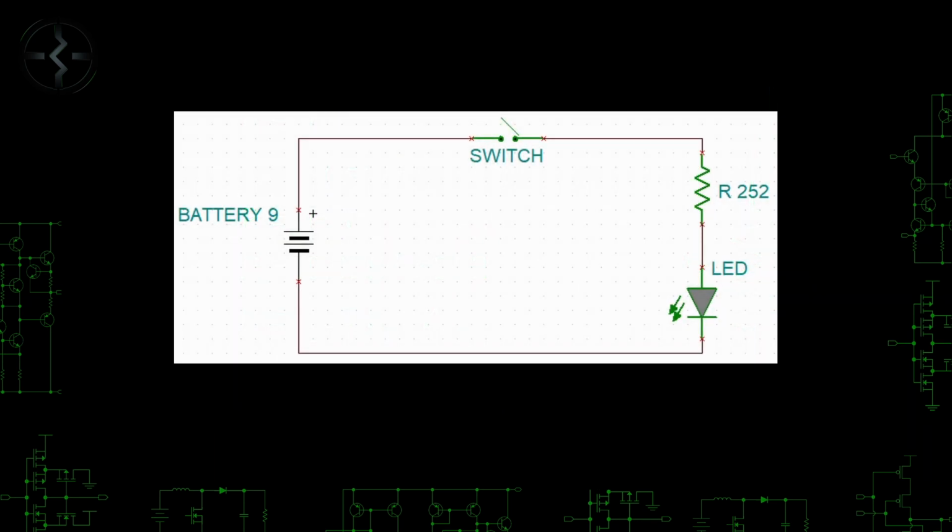At this point, you've got a finalized design for your circuit. The only thing you really had to calculate was the resistor value. Now all that's left is to choose exactly what components we'll be using. We've already got our battery and LED selected, but we need to get our switch and resistor. If you only want to use one LED, this is the circuit you use.